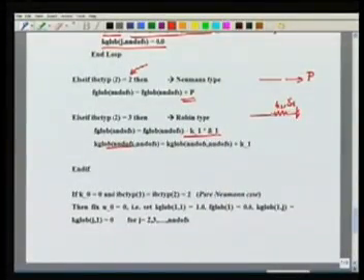So in this case, for the Robin boundary condition, we have the end spring K1 and the end compression delta 1. This again can be applied similar to what we had done at the end x equal to 0, by first taking the last load vector entry, from which we subtract this K1 into delta 1. This is the part of the load, and then to the last diagonal term in the stiffness matrix we will simply add K1.